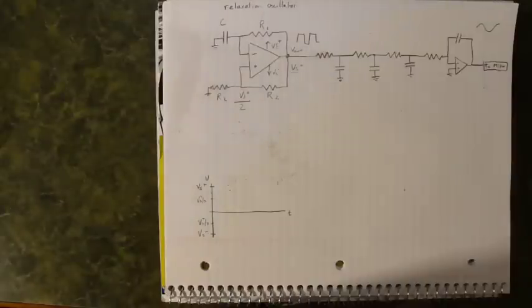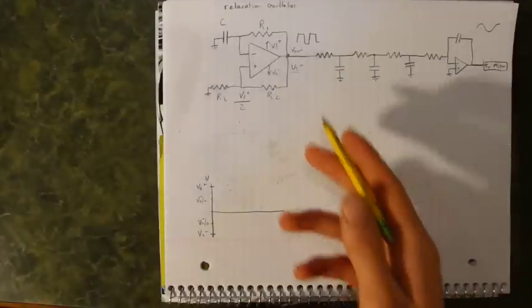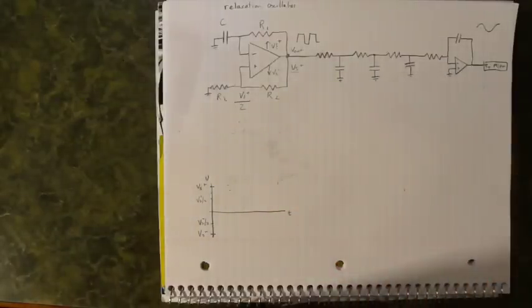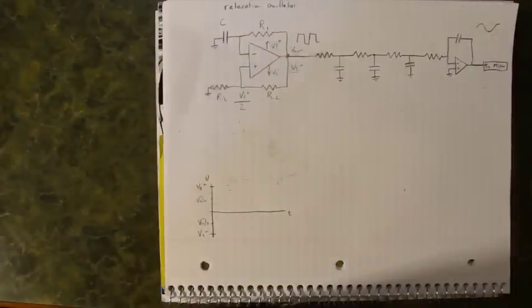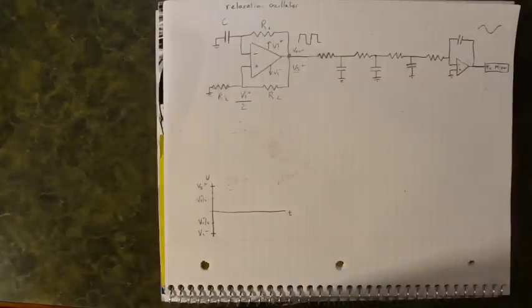Okay, let's look at the oscillator circuit now. Now all three oscillators are going to look similar to this. They're going to have a relaxation oscillator hooked up to a low-pass filter, and this will generate a pure sine wave. Now this capacitor here is what we'll be controlling, whether it's the antenna for the pitch or volume oscillators, or for the pitch reference oscillator, it'll just be a tuning capacitor, a trimming capacitor, I mean.